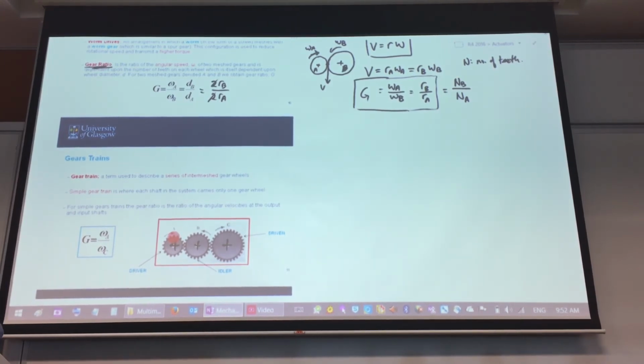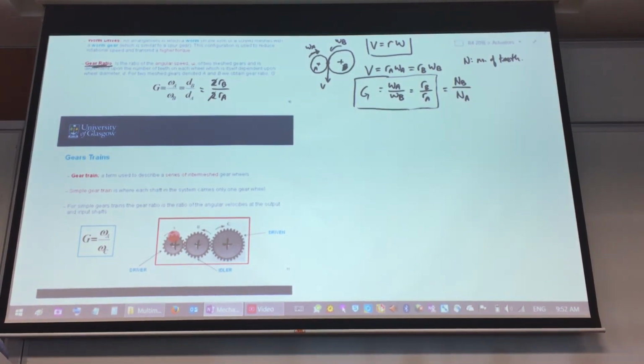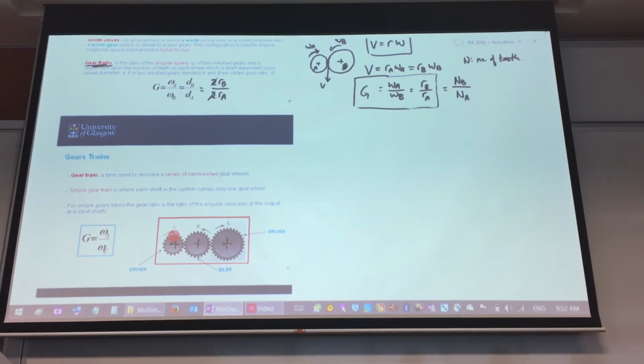So in order to make use of this rotation, in human scale, it's actually easier to use something that's rotating slower. But there's no slow rotating motor that doesn't require additional work, like maybe pulse width modulation control. All these would be costly. So we can use a simple gear ratio or gearing system in order to reduce the speed.